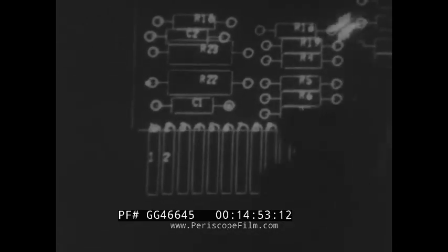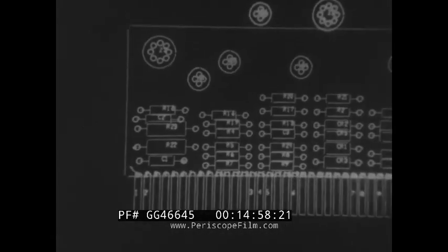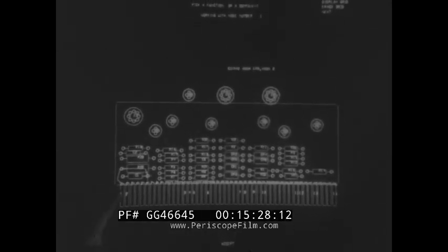The operator has the option of placing the lines on the top conductor pattern, which is solid, or on the bottom conductor pattern, which would be shown as dashed line. The operator can also add feed-through pads for transferring the signal from one side of the board to the other. The lines and pads with the selected node value will continue to blink until the operator has completed making his interconnection. The operator can also delete lines or pads which may be in the way at later times.